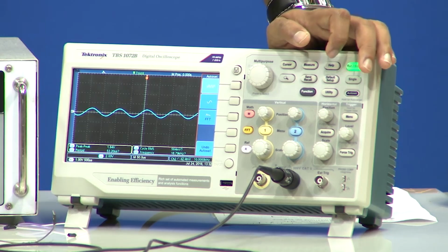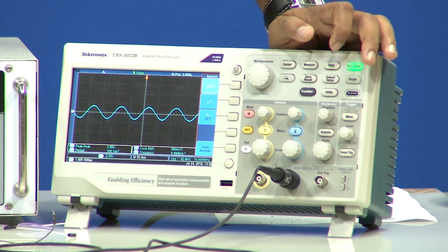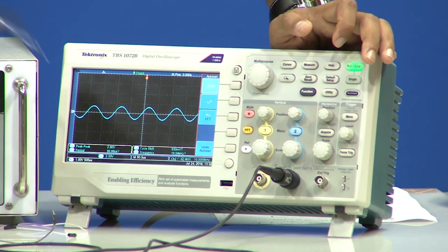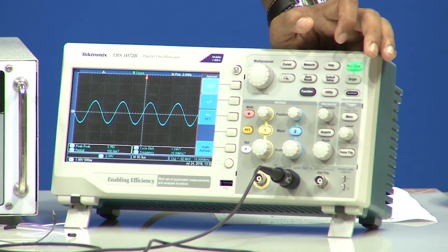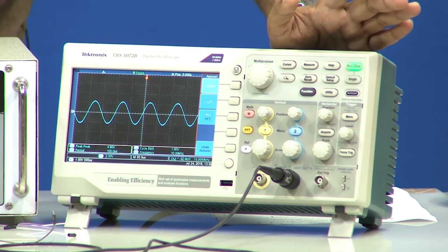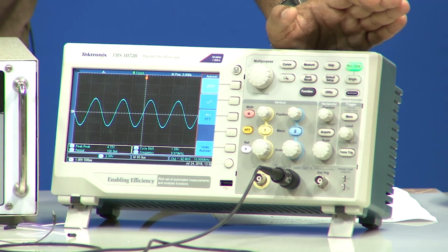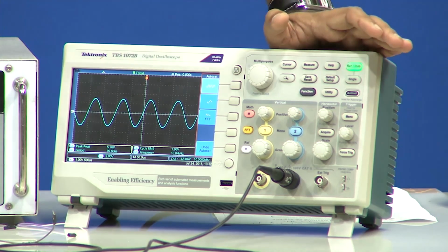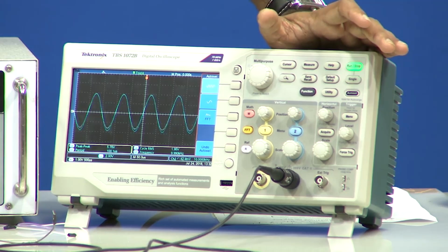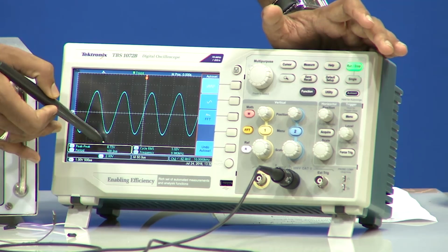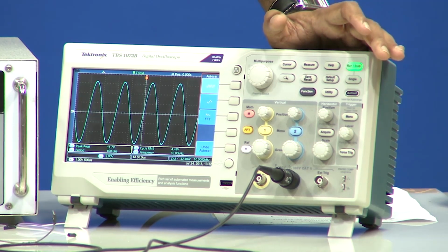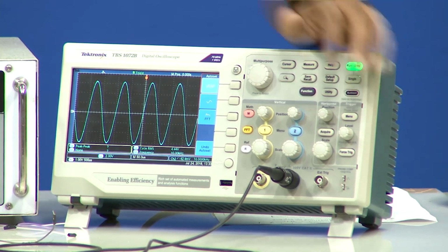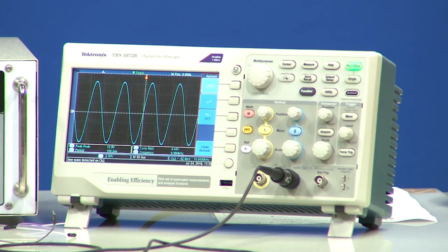Now let me increase the input voltage. I have increased it by 1 volt, to 2.5 volt, and the output voltage is around 2.8 volt. So, it is almost unity gain. Let us keep on increasing the input. If you see, it follows the input with the same phase also. That is why it is called a voltage follower. Now it is 5.5 volt peak to peak, and we are getting 5.7 volt. Then 6.5 volt, 7.5 volt, 8.5 volt, 9.5 volt, 10.5 volt, 11.5 volt. You can see it is still not saturating. I am just using auto scale so that you can see the waveform properly.